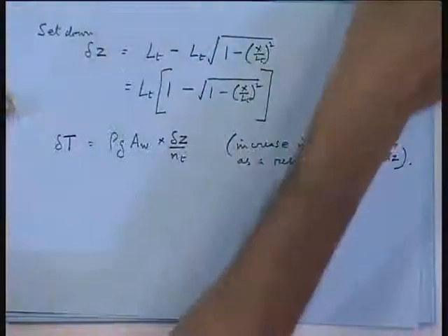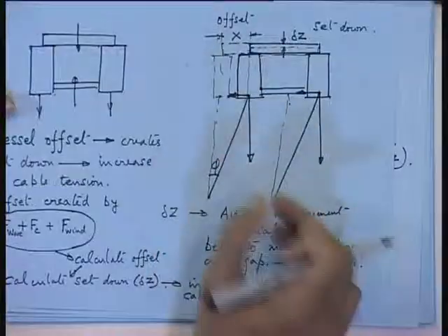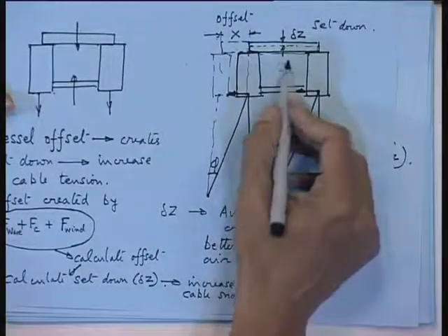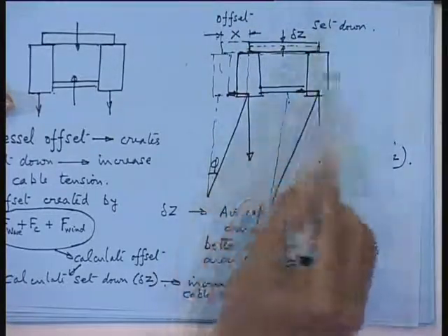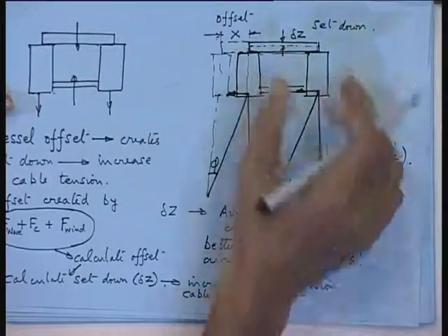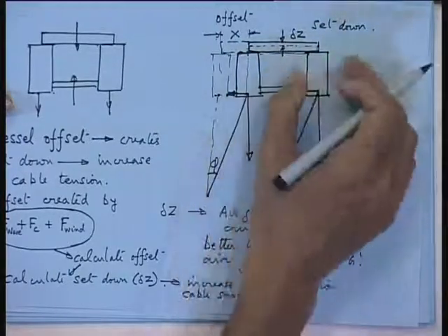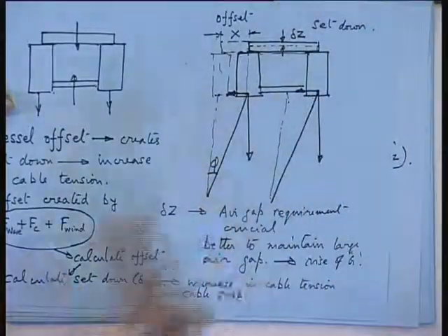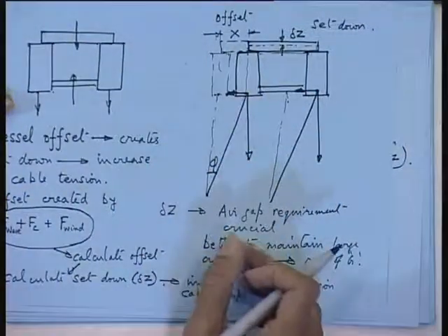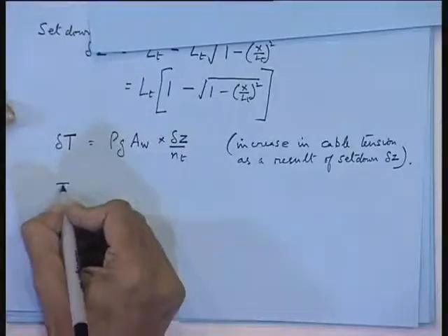But if you pay out this cable, you increase the length of the cable, then what will happen? Your riser is going to increase the length of the riser also. Now, that also is very risky. After a certain increase, the riser cannot accommodate that increase in the length of the riser. So, your riser snap will occur. So, TLP actually you have to be very, very careful about these two aspects.